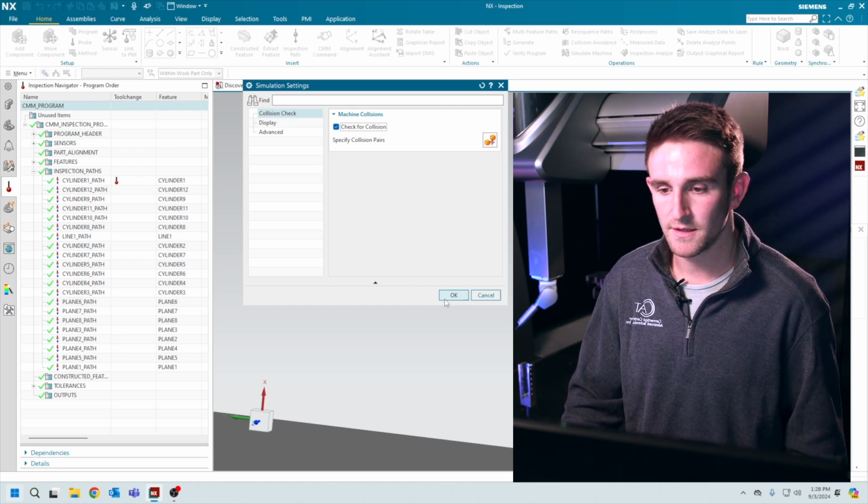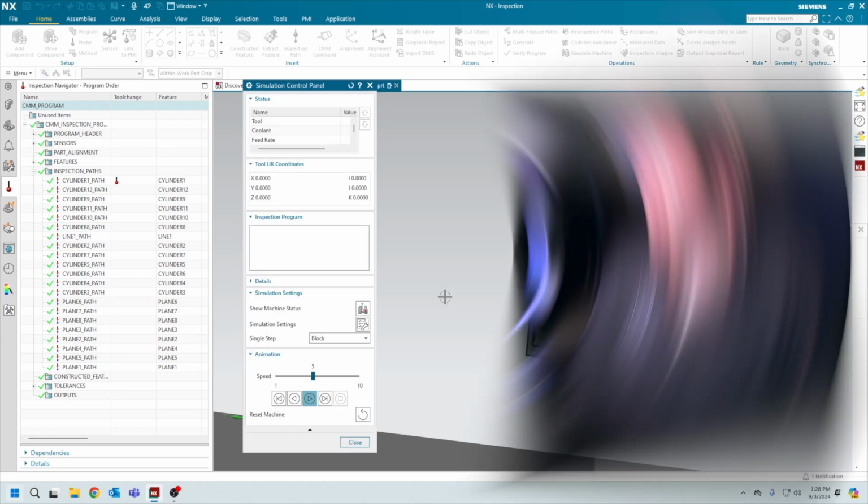Okay, great. And that's just effectively going to help us know what we need to do to make this process safe, because there might be some boundaries within how it's configured already that cannot be avoided, such as maybe the position of the part. Right. If the position of the part's too low to the granite table, the probe head angle will swing into the table trying to inspect a part underneath, and we don't want that.